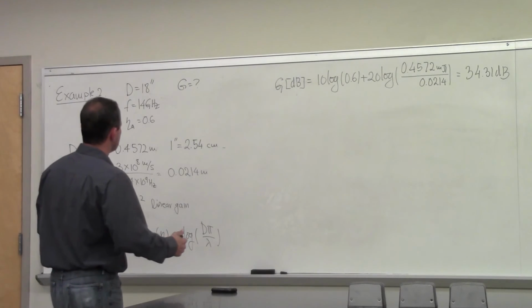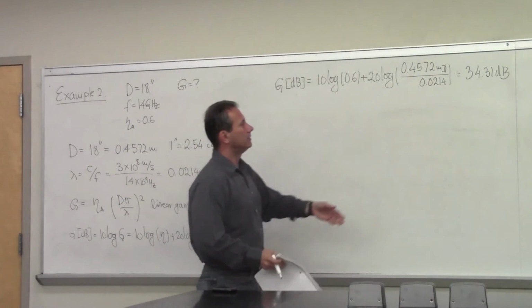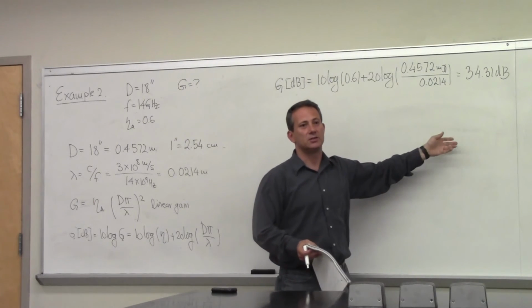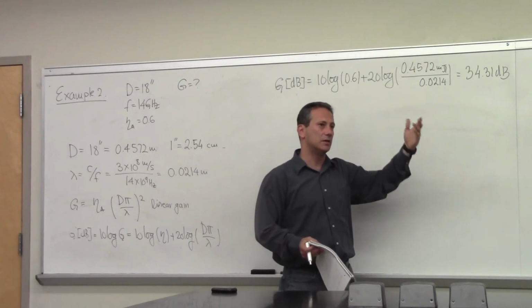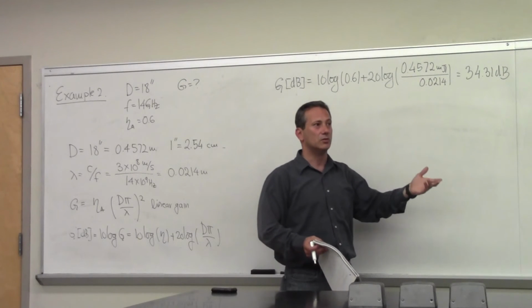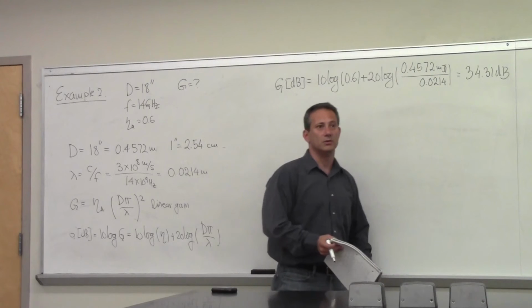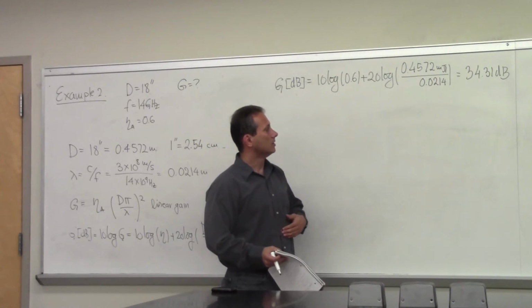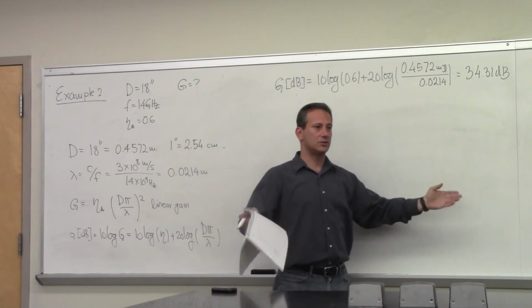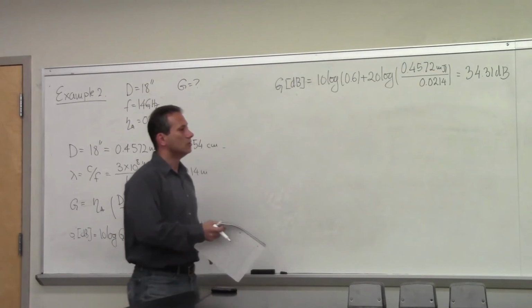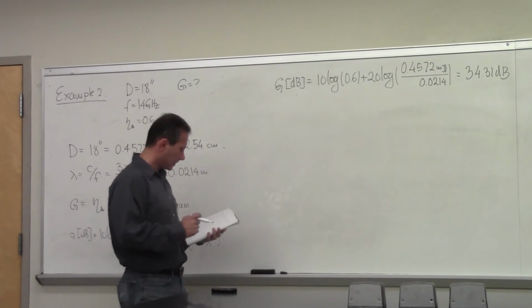And this is huge gain relative to what we encounter in terrestrial systems, in particular cellular systems. In cellular systems, we have base station antennas of 10 to 15 dB, and your mobile antennas are essentially 0 dB or something small. Here, because you don't broadcast, you're just focusing on a small portion of the space, you have a relatively large gain.